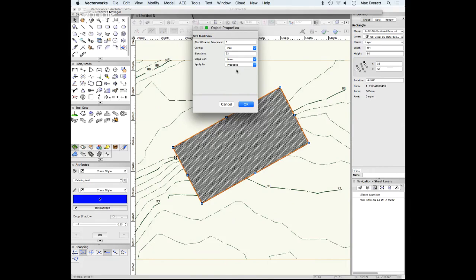And the other tricky bit about site models is you can apply it to the existing or the proposed. So does it need to be meters there, or just 93? Let's just write 93. If it's not letting you do points, just write a rounded number, because it's not letting me do a point either. Yeah, so I've just stuck to 93 meters. And then the next tricky area to remember is what it applies to, which is the proposed or the existing. Because we're adding to the site, I think I'm going to stick it on proposed.